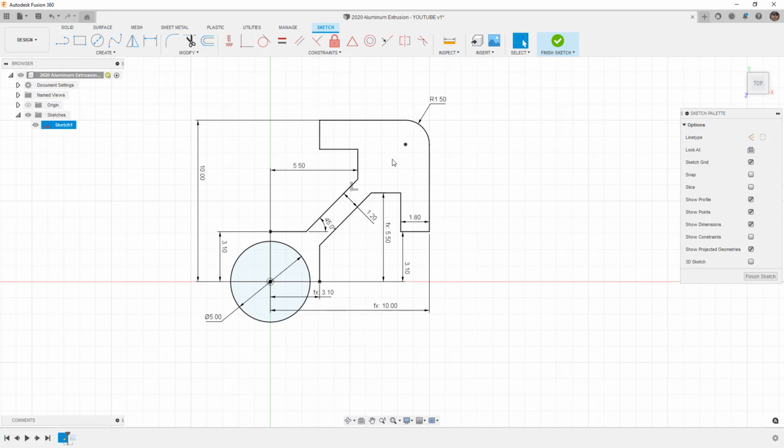As soon as we figure out how to get all the way up to the point where our arc starts, then the x and the y values flip in order to go over here. So this first point is x is 0, y is 3.1 millimeters. This last point is x is 3.1 and y is 0. So we can program in the first set of coordinates. We're going to hard code in the arcs in the corners by their start point, their center point, and the sweep. In this case, it has to be in radians because the units in the back end are going to be in centimeters and in radians.